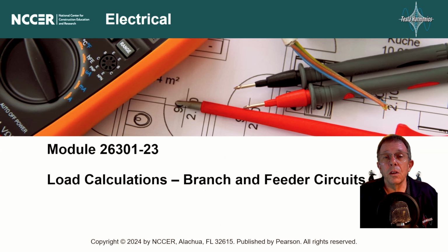Today I want to talk about load calculations for branch and feeder circuits. Calculations to determine the electrical load for branch and feeder circuits are a necessary part of every electrical system design process. The information is used to determine the size of conductors and branch circuit overcurrent protection devices needed in accordance with NEC requirements. Properly sized conductors and protection devices ensure a safe and reliable electrical system.